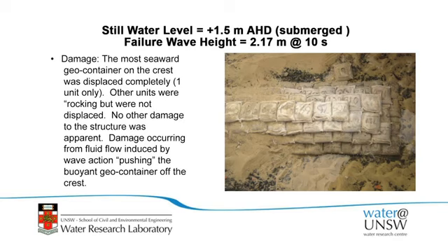You can actually see what happened. Once the structure's under the water, it was actually the crest bags that were damaged. So the earlier test you saw the bottom of the structure started to pull out, but now the bottom of the structure is so far submerged that the waves are going over the top of that. It's like diving under a wave. It's not really doing anything. It's the crest bag that was damaged. So the damage started occurring to the crest.